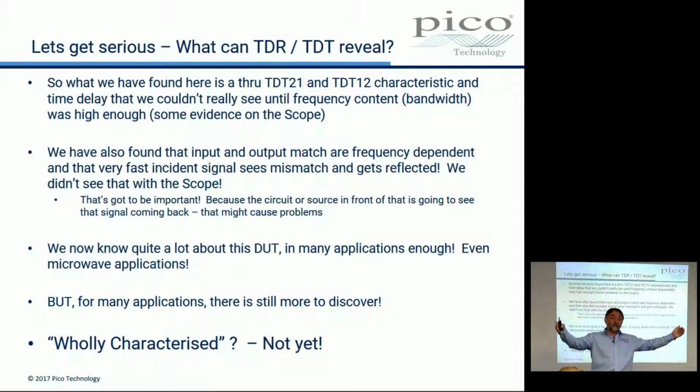It's 100 kilometers long, it's a cable above the ground, it has an impedance, you better match it at both ends, and if you've got a mismatch, you've got a problem. We're not interested in 50 hertz, we're interested in high frequencies, but it happens, it doesn't matter what the frequency is, in other words. In some instances, you need to think about proper network analysis to understand what's going to go wrong.